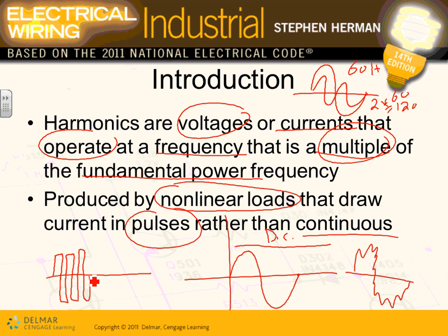Any questions, guys, about harmonics? Nonlinear loads. A nonlinear load is any load that has any electronic device in it. Your laptop, this printer, show me anything that doesn't have an electronic device. That electronic ballast above your head, VFDs, soft starts, PLCs, all these that have any electronic device or semiconductors in them will chew the circuit differently.